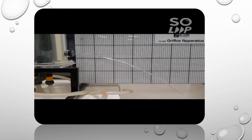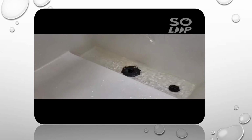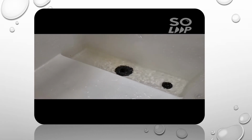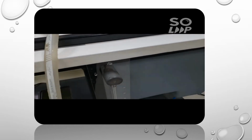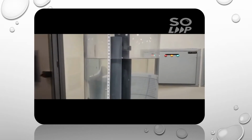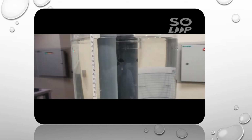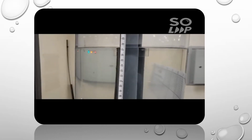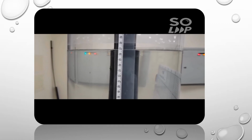After the water level stabilizes, we will measure the water level above the orifice center line. Then we took a photo of the scaled board behind the jet flow to determine the jet trajectory by setting up coordinates for X and Y. We can control the water level by adjusting the vertical shaft to a lower or upper position.